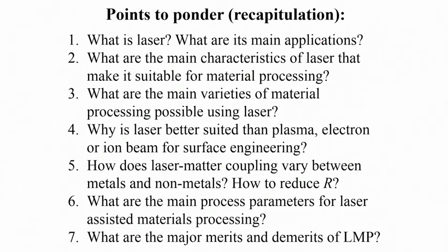So an extremely fast process. The other good thing about laser is that the heat deposition profile is exponentially decaying, so maximum heating at the surface, and only within a few micrometers from the surface temperature falls to room temperature. So essentially you are at a time dealing with a very small volume of the solid, and the rest of the bulk will all be at room temperature. So you are affecting a very small volume.